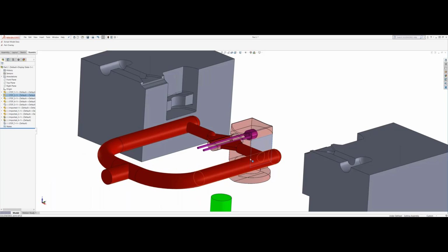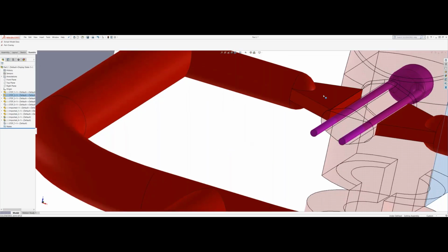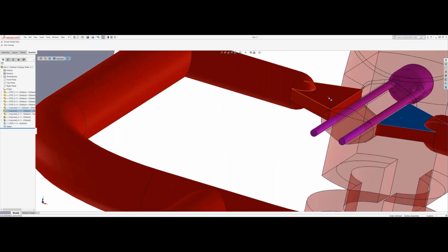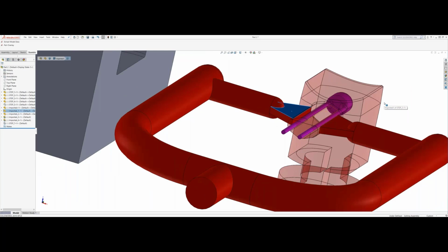Basically, using the two gates on opposing sides is in place so that we're trying to get a nice even flow, so they're not forcing that little substrate piece out of position at any point during the injection process. So that's what we developed here to maintain that position. And as John said, the larger end piece there was acceptable as long as it was fully embedded in the plastic and didn't show a short or a bleed through.